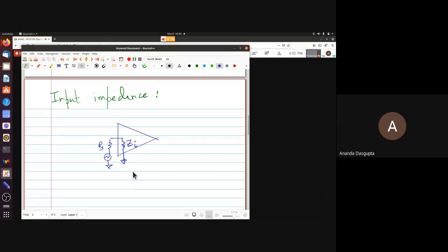Of course, as far as the load is concerned, something which you connect to this side, if you look at it from the point of view of RL, it looks like something quite different. This is something we have described in detail in the last video that I put up. But right now, let's look at just this much. Now, if you have a voltage to voltage amplifier, the important thing is you have a signal voltage that is being fed to the circuit, but the amplifier, of course, does not amplify the signal voltage, right? What does it amplify? Which voltage does the amplifier amplify? Again, a question which somebody should answer. If you have a voltage amplifier, the signal voltage minus the voltage drop across RS.